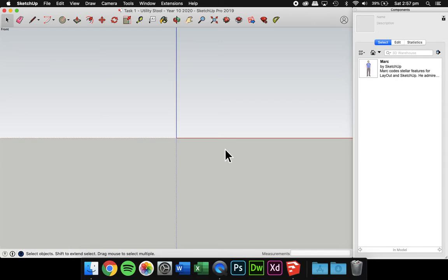Let's get started. We're going to draw the front view of this particular piece. And if you're looking at your drawings, you'll see that this is 360 millimeters long and 42 millimeters high as our starting point. So I'm just going to put in a rectangle. So clicking the arrow here shows me all the different tools I can put in. Selecting Rectangle, click and drag enables me to set a rectangle.